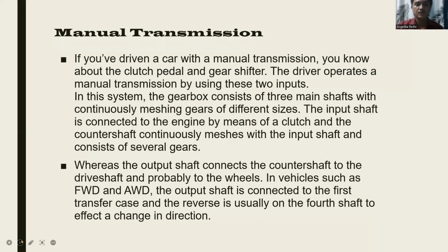Manual transmission. To drive a car with a manual transmission, you need to know about the clutch pedal and gear shifter. The driver operates a manual transmission by using these two inputs. In this system, the gearbox consists of two main shafts with continuously moving gears of different sizes. The input shaft is connected to the engine by means of a clutch, and the counter shaft continuously meshes with the input shaft and consists of several gears,